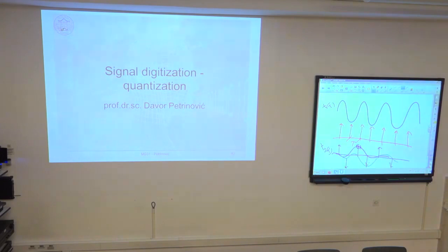So the AD conversion that is used in this RTL-SDR USB stick is a flash converter architecture. Flash converter means that it compares the input value simultaneously to all levels of the AD converter.